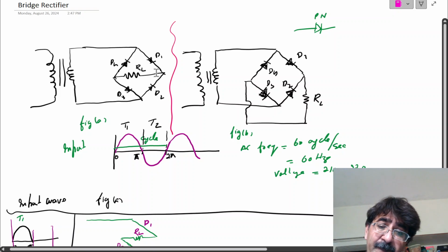So the N part of diode 1 will be less negative than the P part, because the P part of diode 1 is facing the negative ripple coming directly from the transformer without any drop. So it means the N part will be more negative, so the current will pass through D2, not D1.